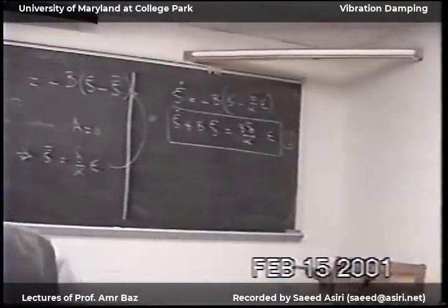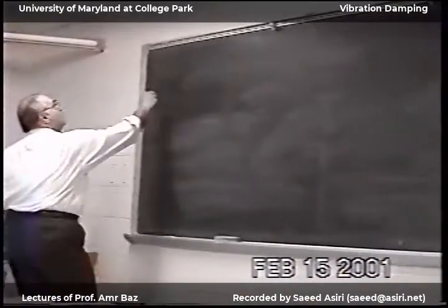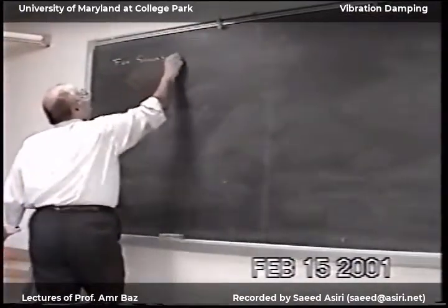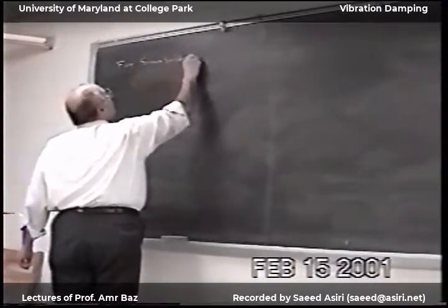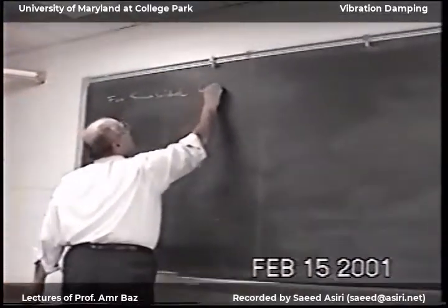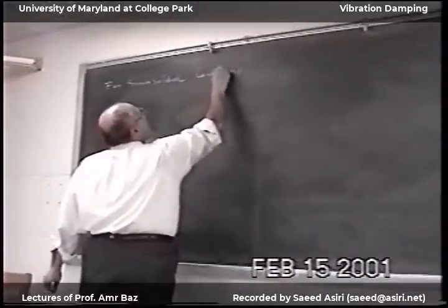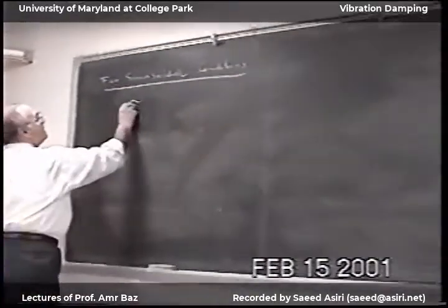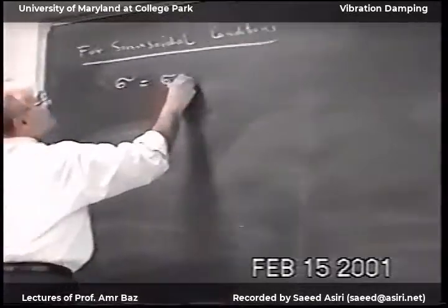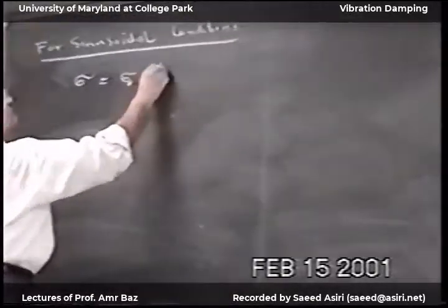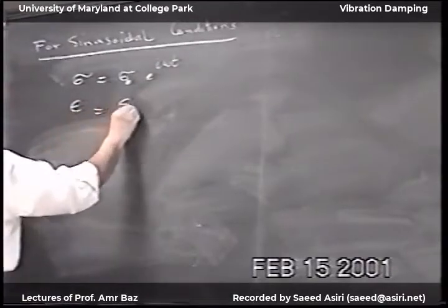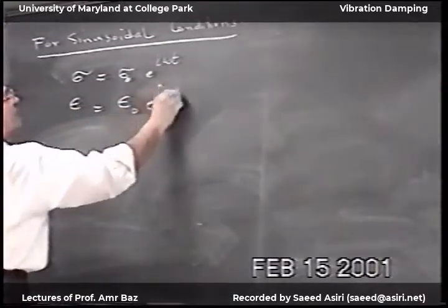I'm going to say now for sinusoidal loading, I have the stress, sigma 0 e to the i omega t, and the strain, epsilon 0 e to the i omega t.